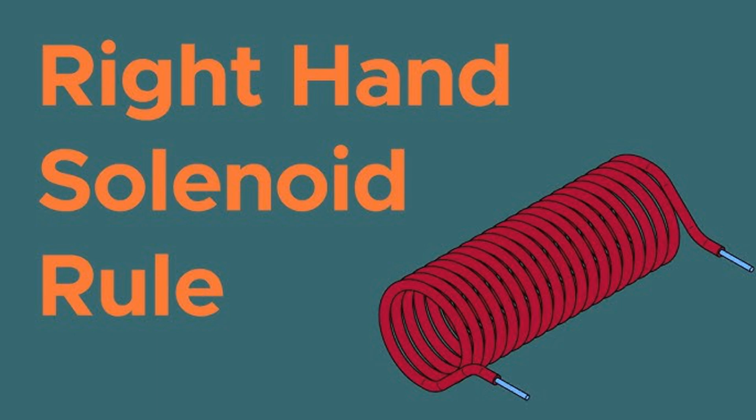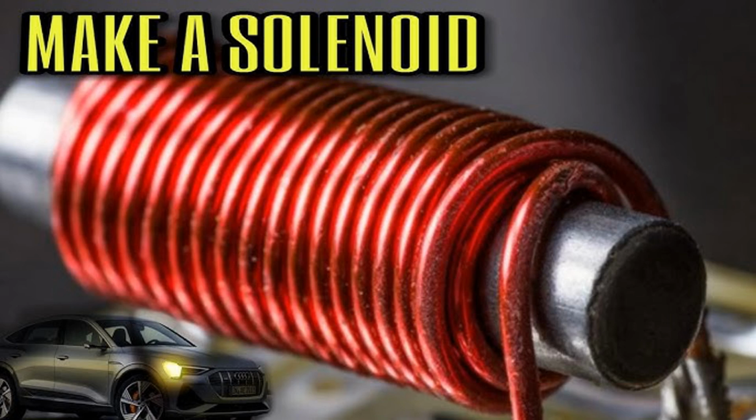6. Bobbin, or coil former. Material: typically made of plastic or non-conductive materials. Function: the bobbin is the structure around which the wire coil is wound. It holds the wire in place and provides insulation between the coil and the core or frame. The bobbin also helps maintain the coil shape and protects the winding from damage.